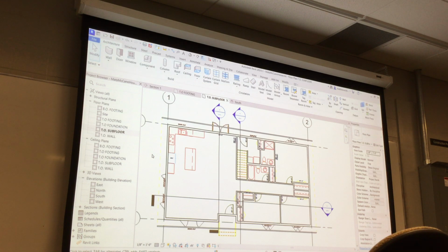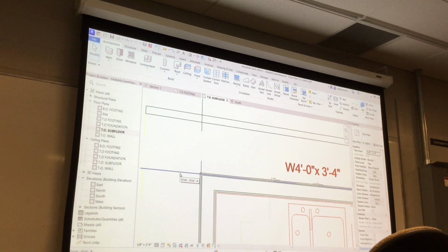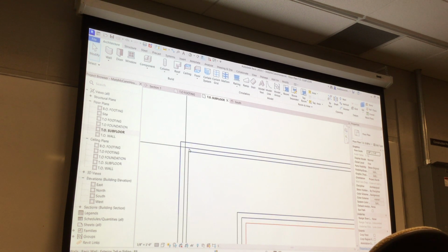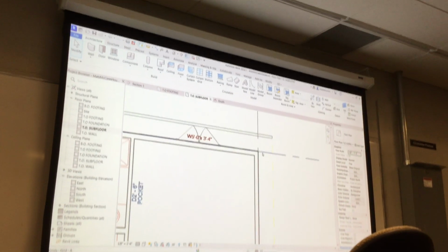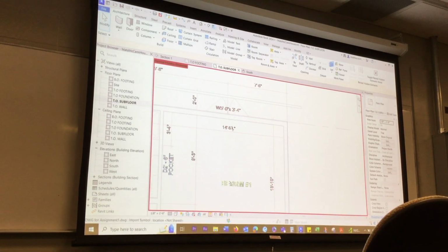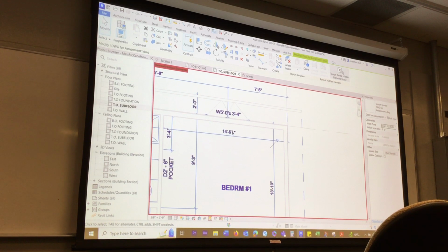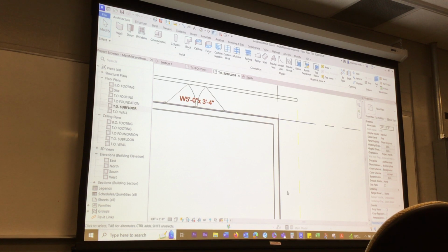The other thing is these grid lines. They need to be on top of the DWG, which these are. But where do I wanna start drawing my model? Outside of sheathing. Okay, so that has to be, there were quite a few that had this mistaken. So there's two things you gotta do here. One is you gotta make sure that the grid lines are on the DWG. I guess it wasn't hidden anyway. Make sure that it's on the DWG, but also make sure you draw your model on it.